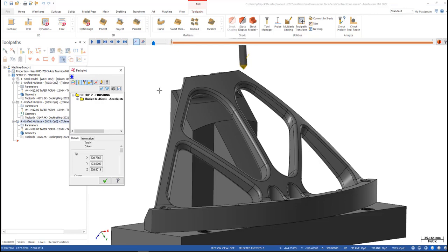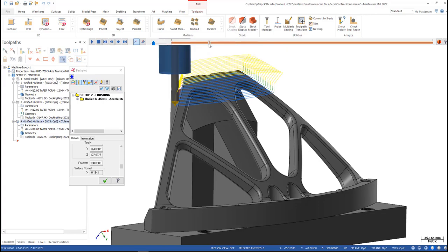Now once I start to run this toolpath, I'm going to see in my details here, my feed rate especially is what I want to watch. So as we're going, I'm just going to speed this up a little bit. Once we get to the end here, we're picking up a feed rate of 500. We're going through the center here at 500 where we're really not establishing anything, and we're cutting across our surface and we're still going 500 inches a minute.